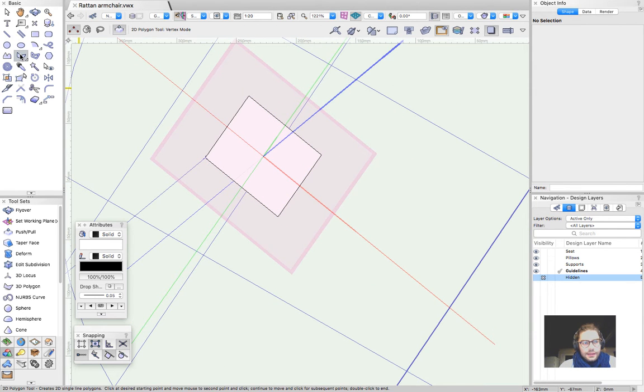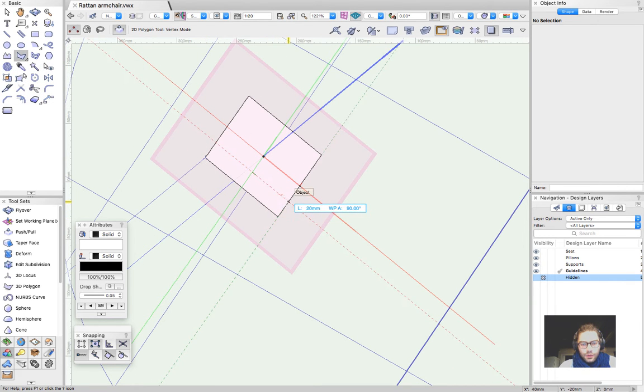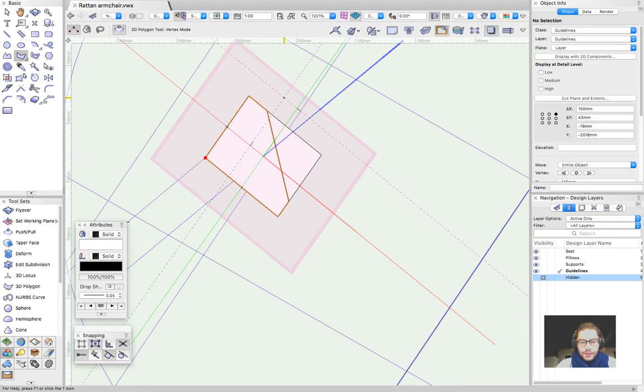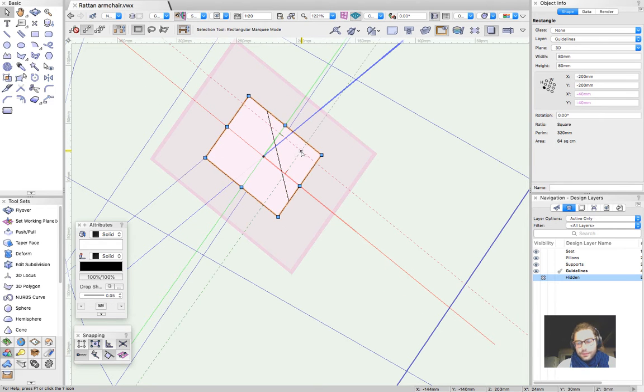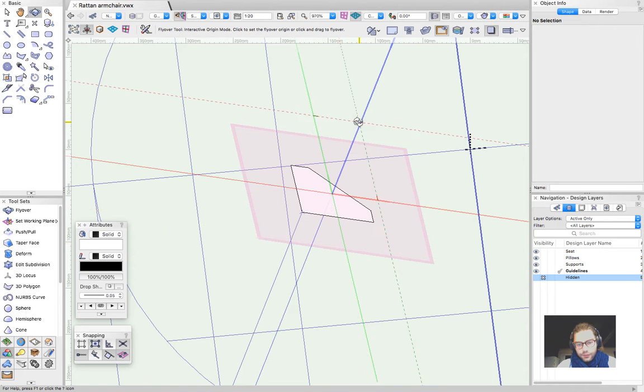and let's grab the Polygon tool. So this piece definitely should be straight. Then we need to decide on the distance. So I'm going to type in 20. Then it definitely goes 45 degrees, comes to the straight piece, goes 20 millimeters toward this direction and goes back to the base point. Let's delete the previous rectangle. We've just created the platform shape.